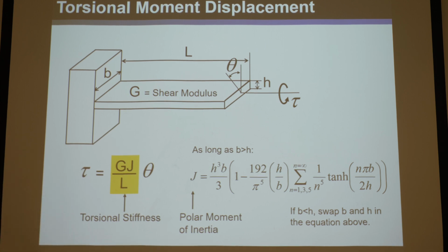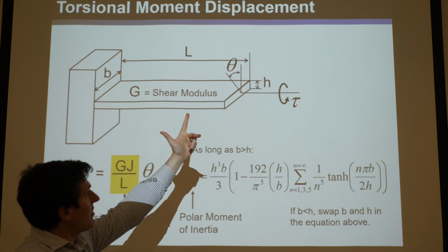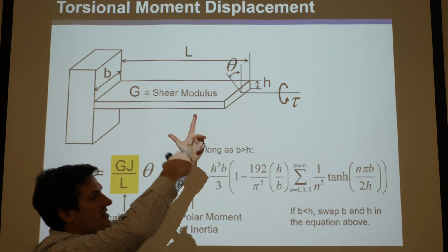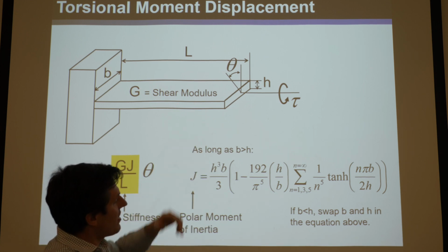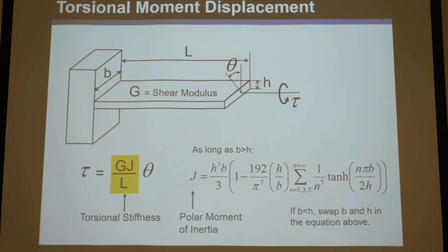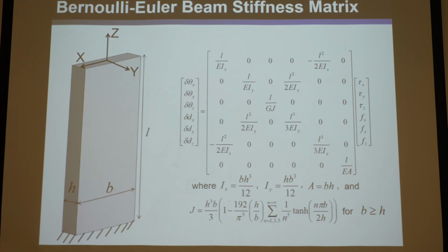Okay, so those are all the different kinds of stiffnesses. In all, there's essentially a number of equations. I believe there's 10 equations that will characterize the full stiffness in all 3 independent axes of this beam. If you put a coordinate system at the end, and if you plot all the different forces and torques and displacements and thetas in all these 3 different directions, you get a number of equations. And they can be captured in this 6 by 6 matrix.